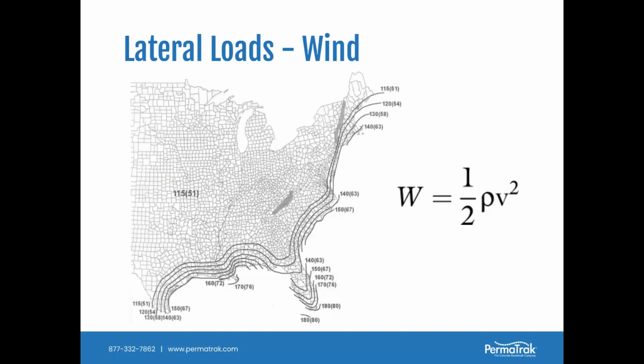So those can be very, very critical for uplift as well as lateral loads. So you do need to consider lateral loads. Typically, the wind load is going to be the governing lateral load, not only to the system, but then it also has to transfer down to the bottom to the pile in the foundation system also.